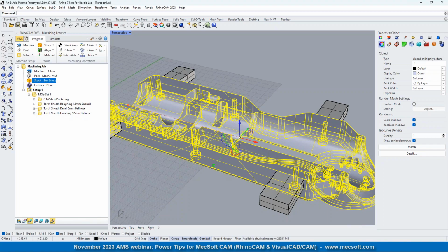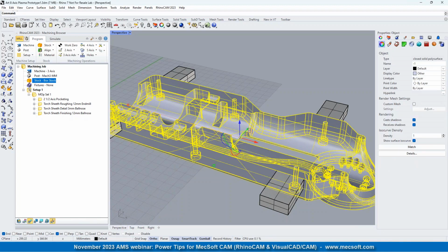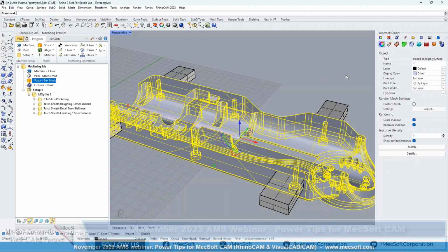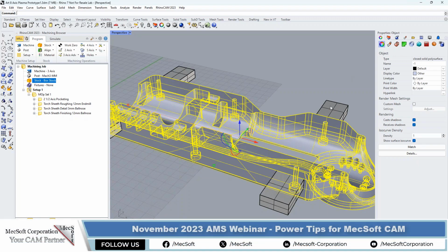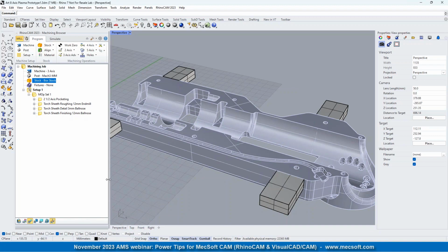So if you see polysurface, obviously you know it's a solid model. It's a NURBS surface model, which is the most accurate model you can work with. I don't have a mesh model up, but if you had a mesh model and looked at the information, it'll tell you it's a mesh. So you just want to be aware of that if you're not sure whether you're getting a mesh or not, because working with a mesh has another set of complications that you need to deal with.